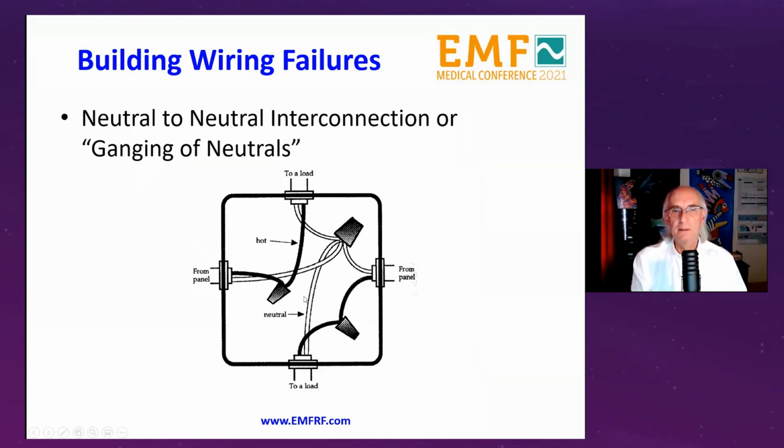And here's another coming from the panel going to some other electrical appliance. And the neutrals are put together. That should not be the case. There should be 2 nuts, one connecting these 2 wires and one connecting these 2 wires. And then the magnetic field problem will dissolve itself. So in other words, wiring issues in buildings we can address relatively easily.